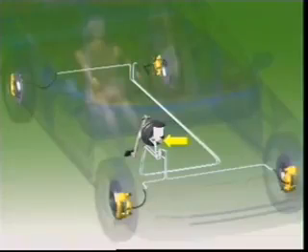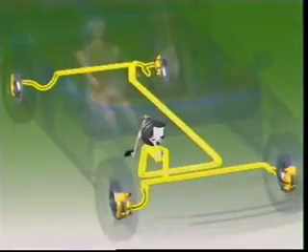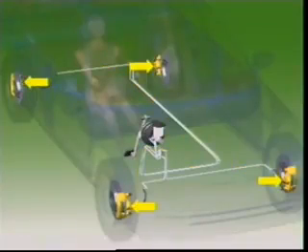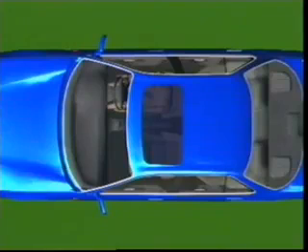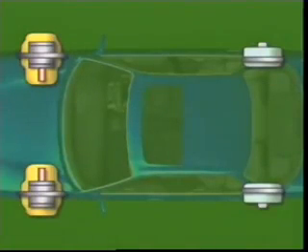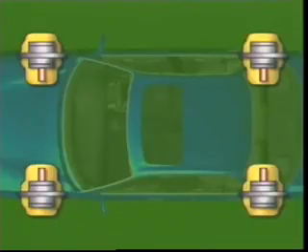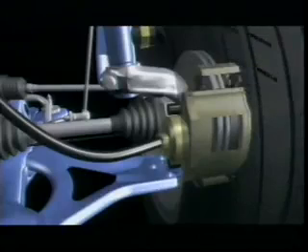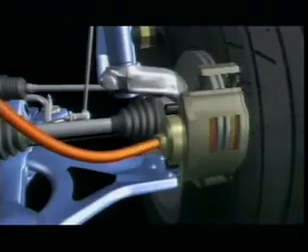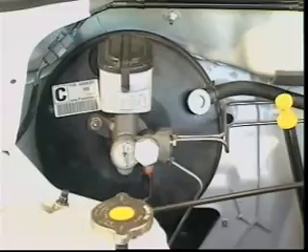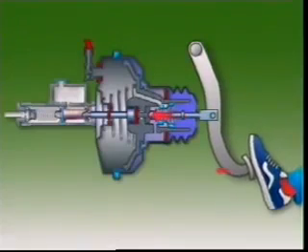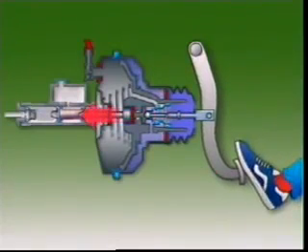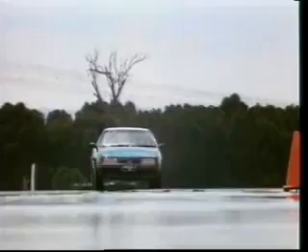The brake pedal operates a master cylinder. Hydraulic lines and hoses connect the master cylinder to brake cylinders at the wheels. Most modern light vehicles have either disc brakes on the front wheels and drum brakes on the rear, or disc brakes on all 4 wheels. Disc brakes require greater forces to operate them. A brake booster assists the driver by increasing the force applied to the master cylinder when the brake is operated.